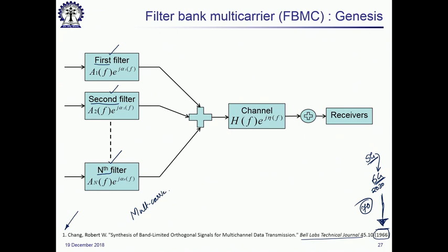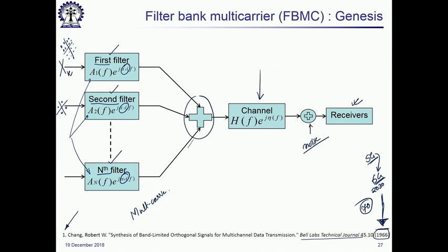Right. So, in each of the multi-carriers, what you will find is that there is also e to the power of j alpha 1, e to the power of j alpha 2, e to the power of j alpha n, indicating the changeover in the different frequencies, and these A1, A2 and An indicate the amplitude gain factors of these particular filters. Right. And they all add together. So, overall we do not see any difference with the basic structure as in OFDM. That means there are parallel subcarriers coming in, each subcarrier choosing a particular constellation point from the constellation which is to be used. Right. And there is no such restriction that all the constellations have to be the same, they can be different constellations. Then there is a channel, and finally there is addition of noise, one can think of at the receiver, and the reverse processing has to happen at the receiver.